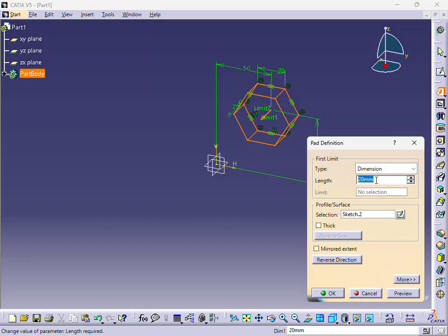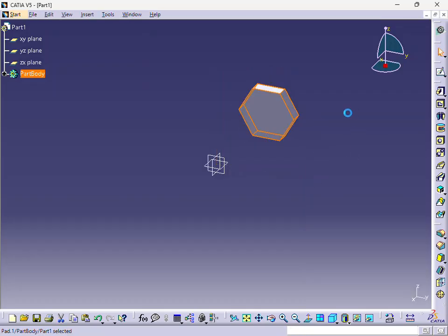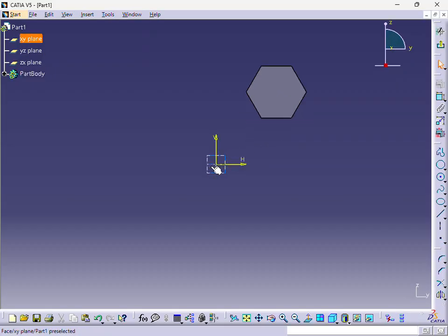If I exit this sketch and build something out of that sketch, let's make a little wedge here, some little block. If I go to build my second sketch, if I use the same regular standard sketch, select on that flat surface or even this datum plane, the origin is going to go back to wherever the system defaults it to, which puts it back here. I want to be able to put a hole in the center of this part. Well, the problem is I need to find where that hole is. Now, I could do the offset distances and be able to get it there, but I don't want to have to reference that. I want my sketch to be put so that the vertical and horizontal axis is in that position instead.